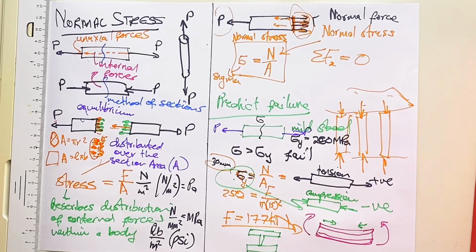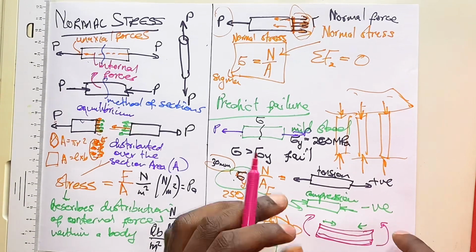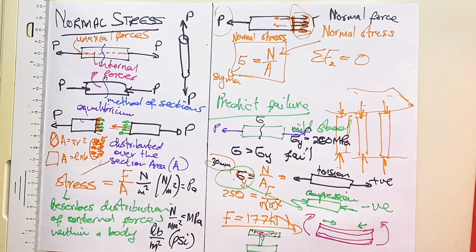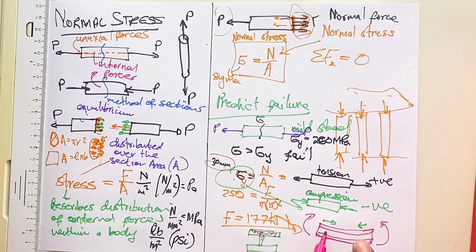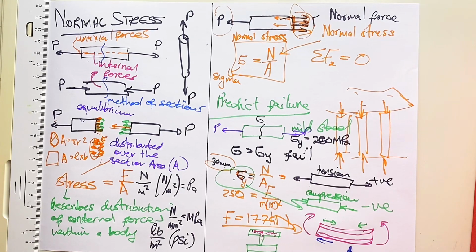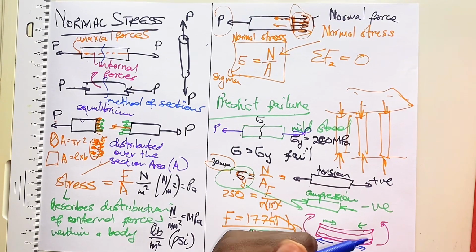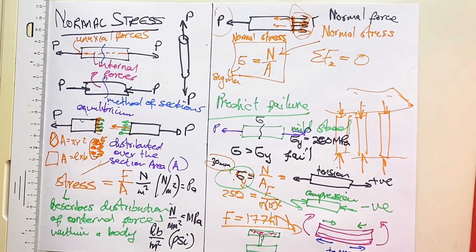At the top here, you will experience compressive forces because the moments on the sides, when they act at the top, make it more compressed. However, at the bottom it will start to stretch and you will experience tension.